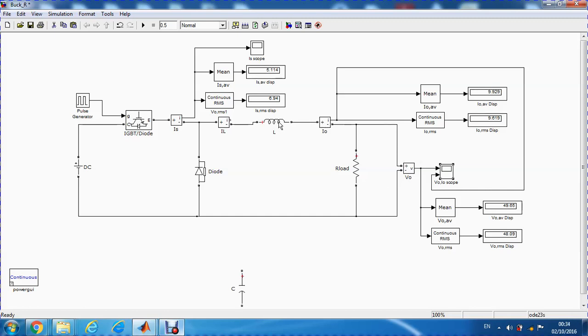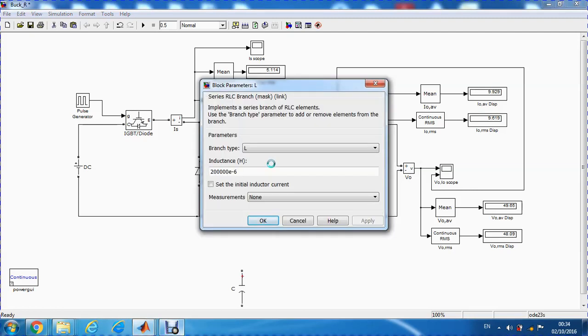But what we have done here is that we have increased the inductance value to a value that is not really reasonable in our practical life. Finding an inductor with that value is going to be a very big problem. So even though we can achieve it, it is 0.2 henry. That's too much. So what we will do is go back again to 100 microhenry.